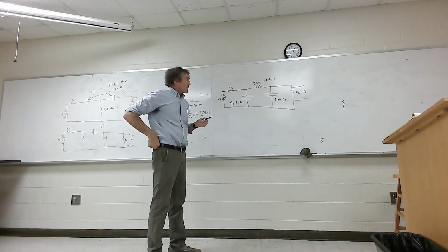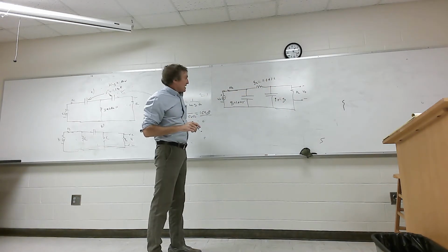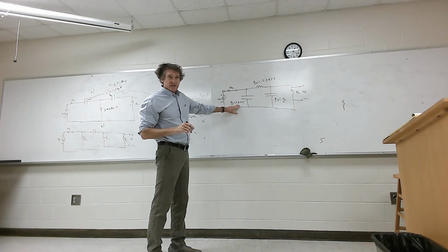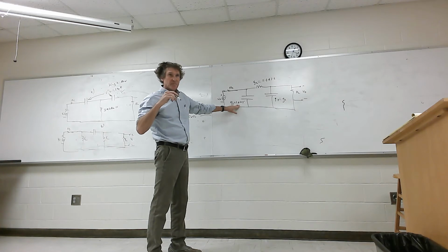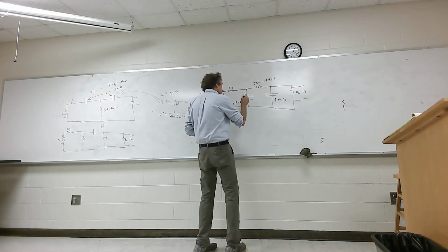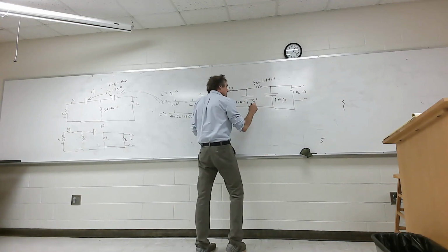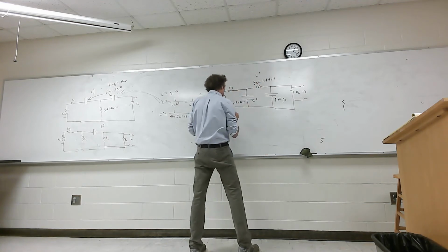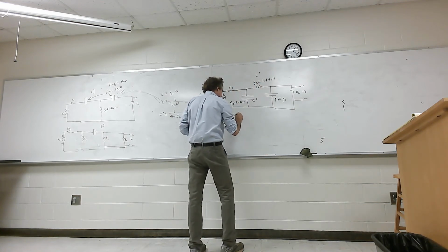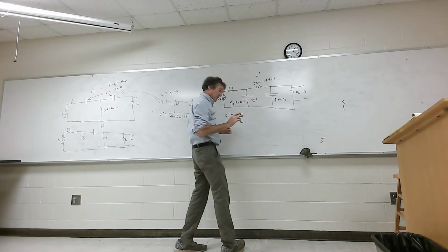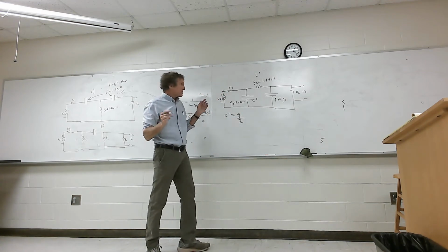Okay. Now, next, after that, we're going to go ahead and get the values of this capacitance, C prime, not C double prime, just the value of the normalized capacitance value. So, to get this capacitance right here, which is C prime, this will be my L prime. C prime is going to be G1 divided by Z naught. You all with me on that? And Z naught's 50.